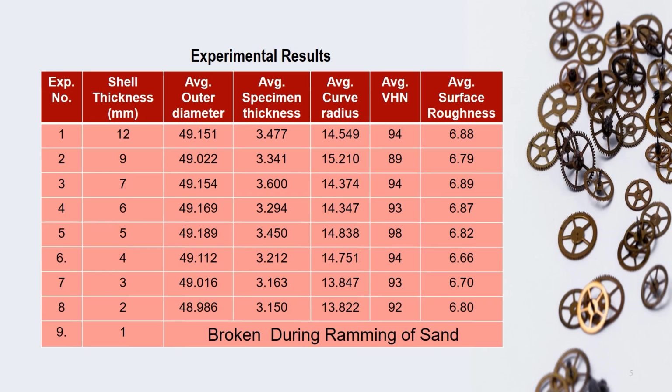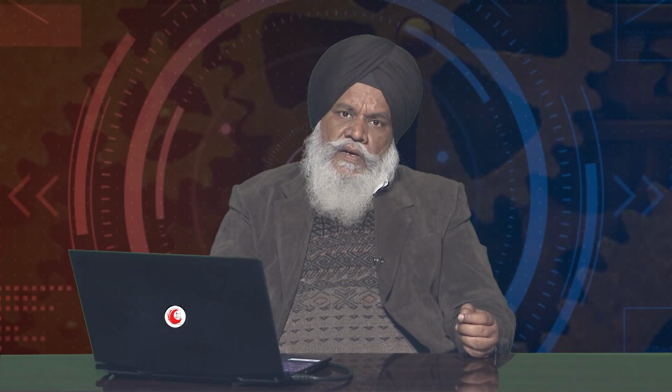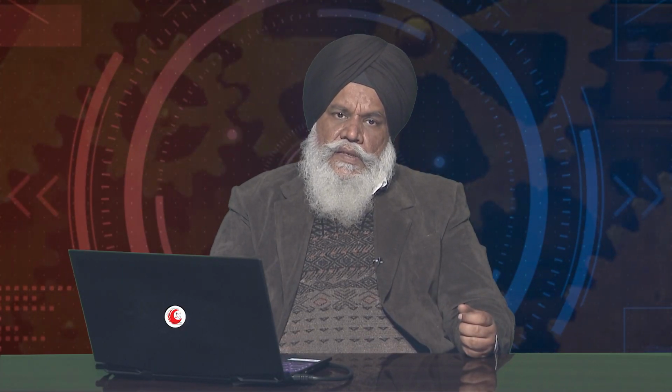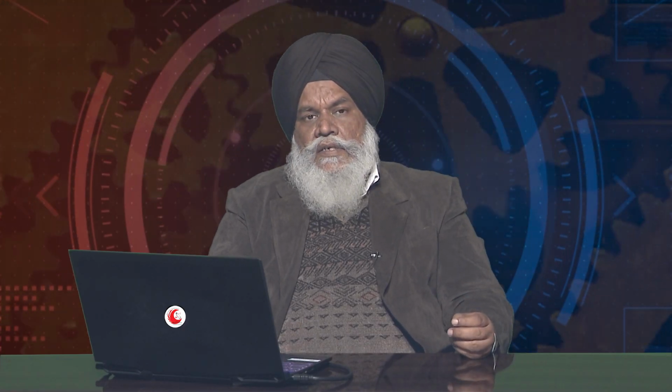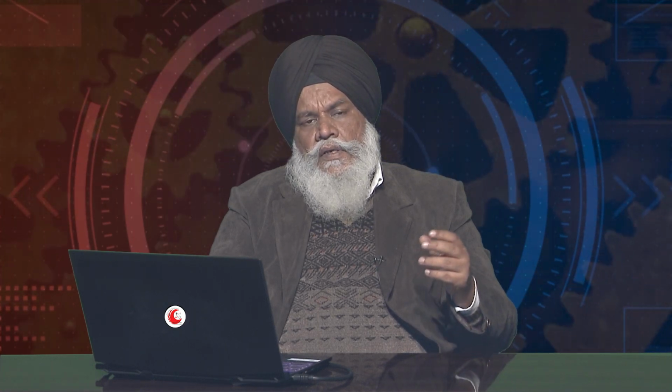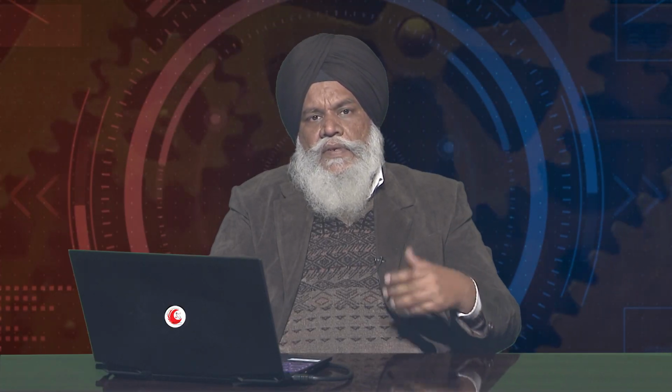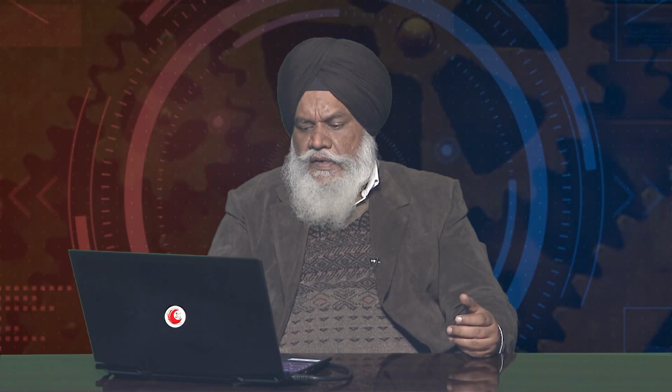So what we observed, in this special case, is that the sample was broken when I put the shell wall thickness below 2, and we tried to reduce it to 0.5 even for some other molten metal cases. So the basic idea is, for the different densities of metals, we can control the shell wall thickness and basically control my process, which will lead to a more cost effective process.